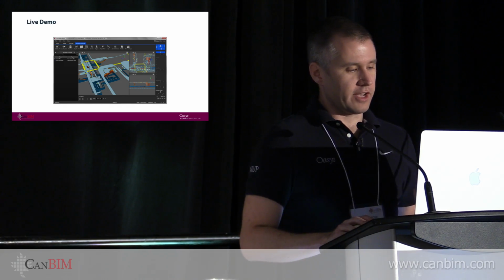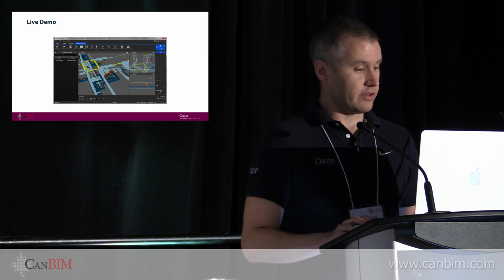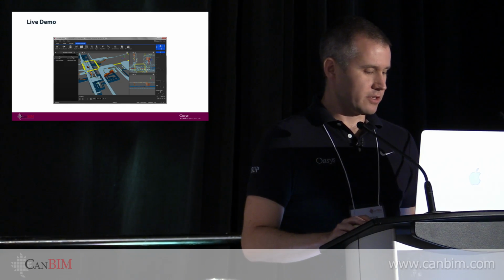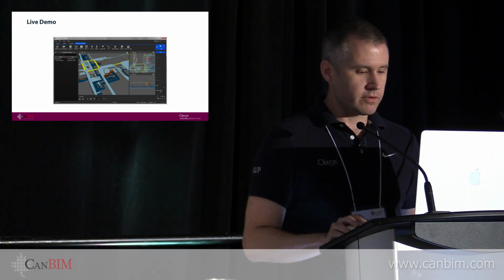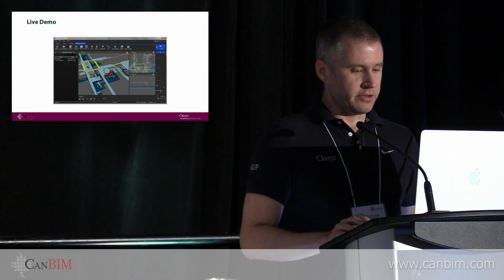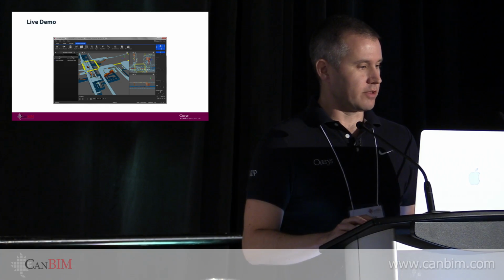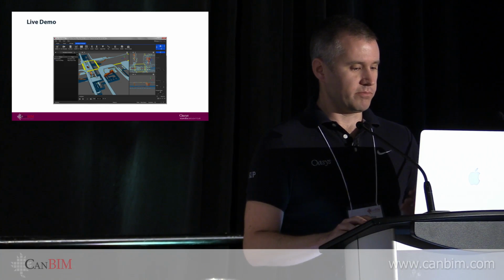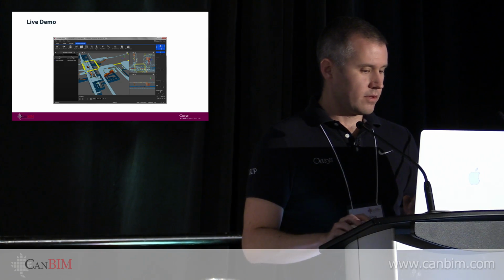The other thing which is really important is having an object which represents where agents are going to start and end their journeys. So to do that, we create portal objects. So we'll have a start location and an end location. And now what we need to do is specify for the software where agents are going to start and where they're going to finish. And so to do that, we look at activities and say, right, we're going to create a journey going from the right-hand side to the left-hand side of this. So add that portal.